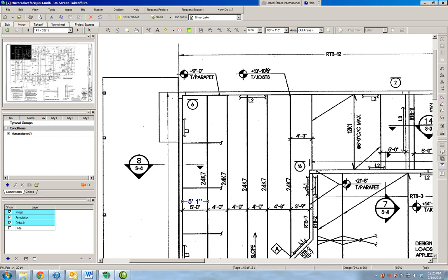This here, this one and this one seems to be a different one. This seems to be 12K1. Now, if we do want to see a cross section of this section to make sure there is no 24K7 here at the edge, we can look at drawing S4 detail 8.